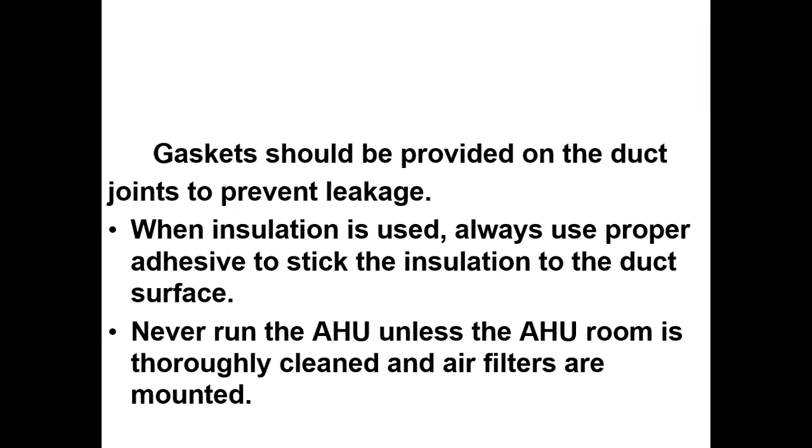At the same time, a gasket should be provided. It's like a double tape itself. So this tape should be properly stuck around the ductwork itself, and you can connect the other duct onto that gasket. So that's how the leakage is prevented.